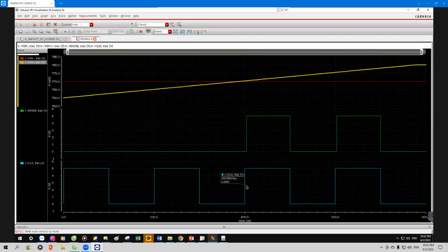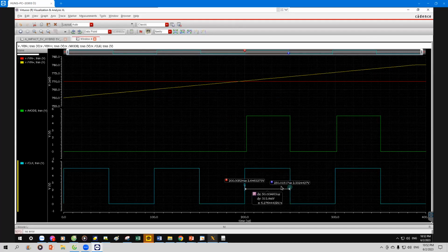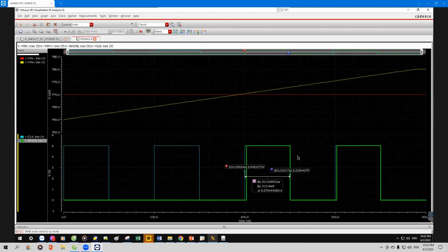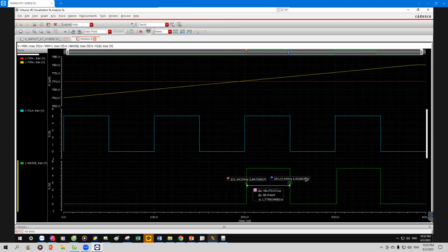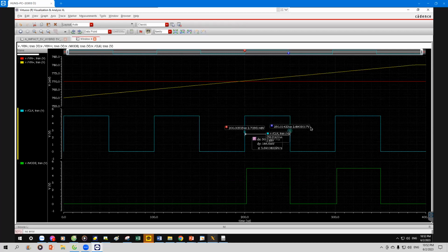Okay, when I change to a larger pulse width, from 2 microseconds to 15 microseconds, the output will be correct. Almost the output pulse is similar to the clock. So remember, you should consider the pulse width of the clock also to run.